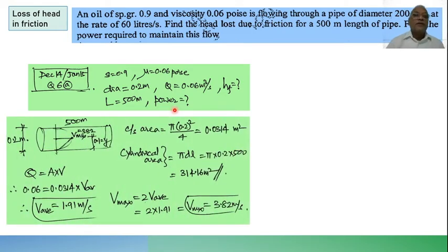Okay, there are many things which are new to you. You can note down. So here I have drawn the diagram showing the velocity distribution inside the circular pipe. So that is the discharge, the velocity diagram. At the periphery the velocity is 0 because of viscosity. Hardly there will be any velocity. Velocity increases, you can just see here, right? It will be maximum at the center.